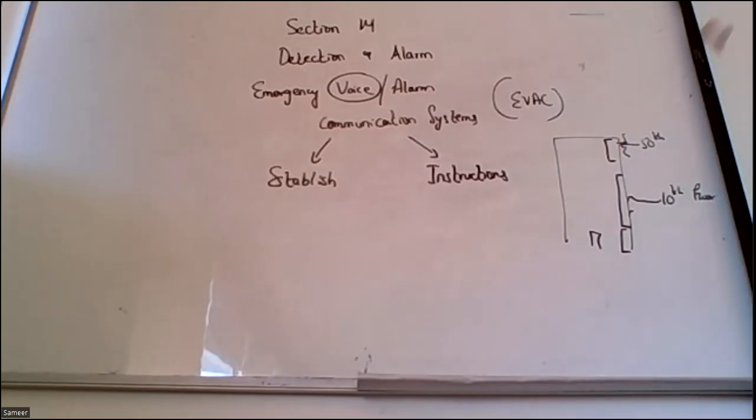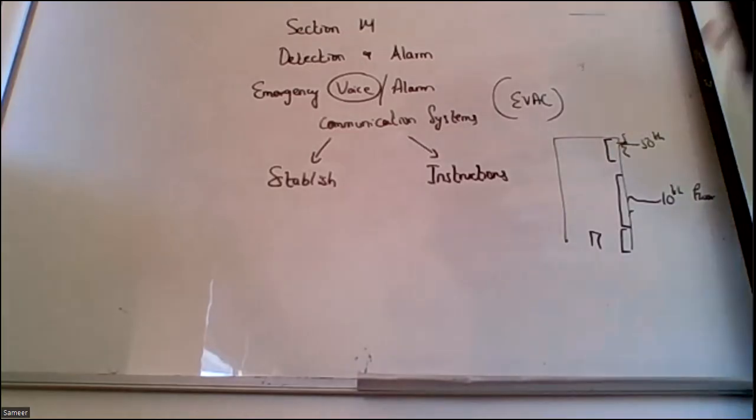So if I want all the people to evacuate on a staircase, the evacuation time will be far greater than 1 hour. It is going to go 1.5, 2 hours even. If a stampede situation occurs, then it is an even worse scenario. People are trapped. So for that purpose, I need to give them instructions. That is the purpose of evac systems, emergency voice alarm communication systems.